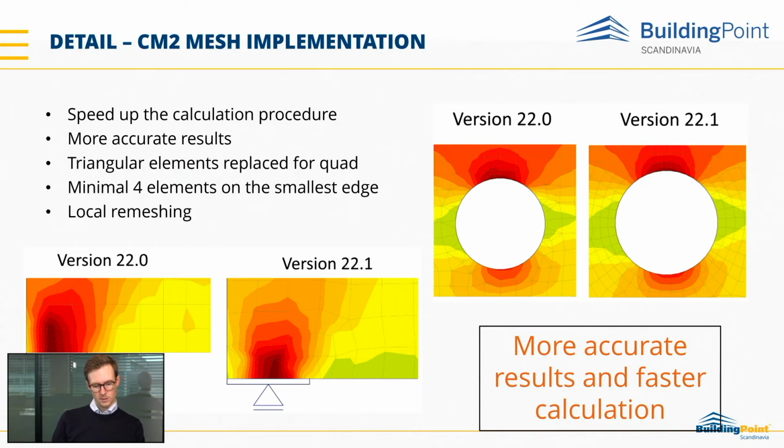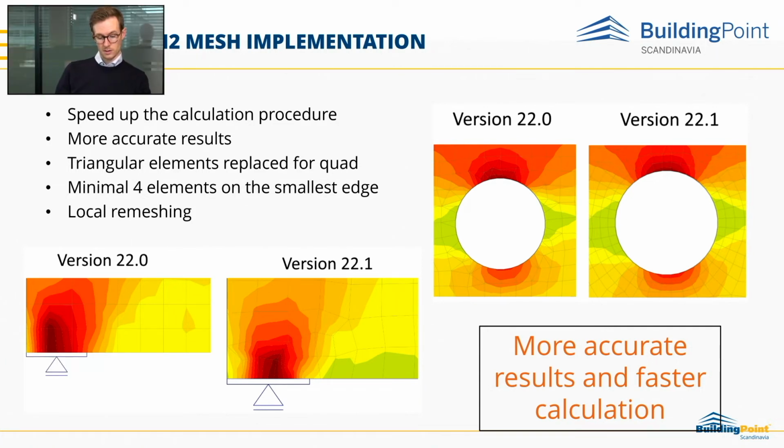Yeah, the mesh is essential for every FEA application. The number of elements, type of the elements, and quality itself lead to some level of discretization issue compared to continuous solutions.